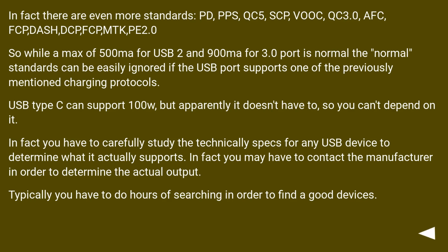In fact, there are even more standards: PD, PPS, QC 5, SCP, VOOC, QC 3.0, UFCS, FCP, DCP, MTK, PE 2.0. So while a max of 500 mA for USB 2 and 900 mA for a 3.0 port is normal, the normal standards can be easily ignored if the USB port supports one of the previously mentioned charging protocols.